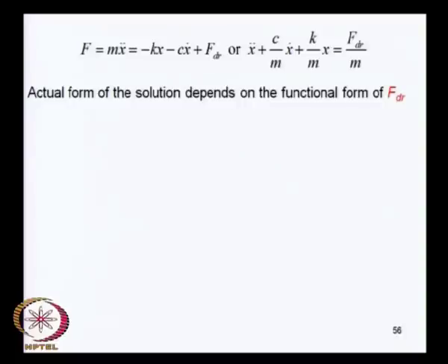Of course, it depends on what kind of damping force exists in the system, and I already discussed in our previous class that the damping force minus c x dot is not a term which comes from first principles, but it is some approximation to the total net effect of the unspecified degrees of freedom that you have not taken into account in setting up the equation of motion. So, it is a net result of all of that, but we will stay with that form for the damping force, which is minus c times x dot.